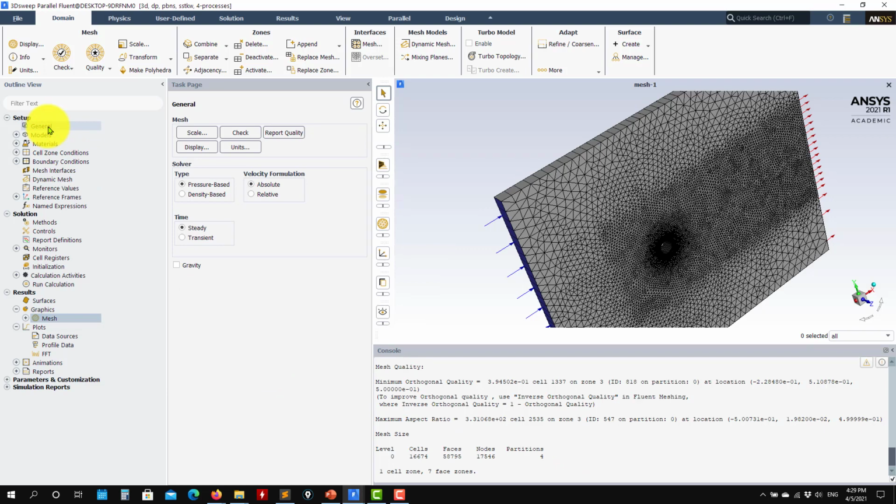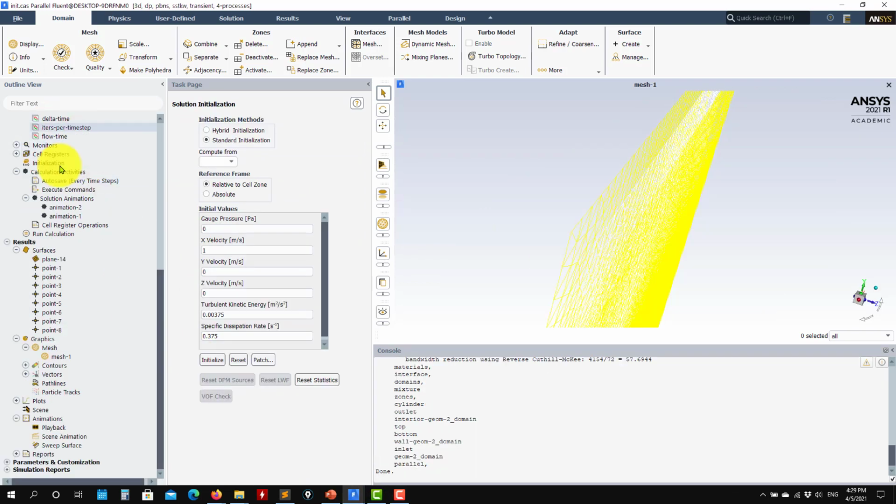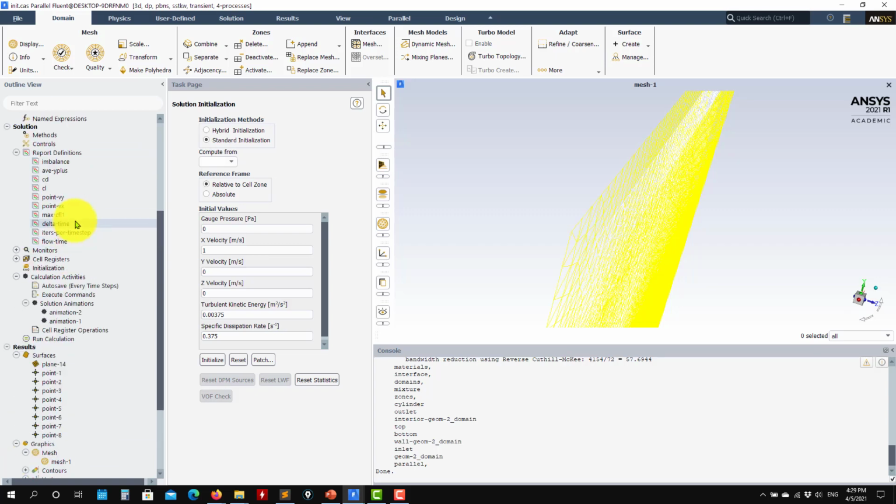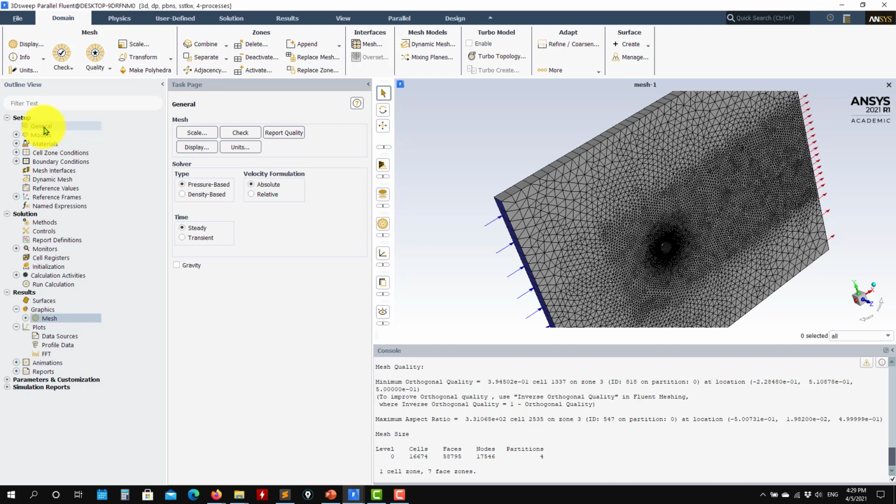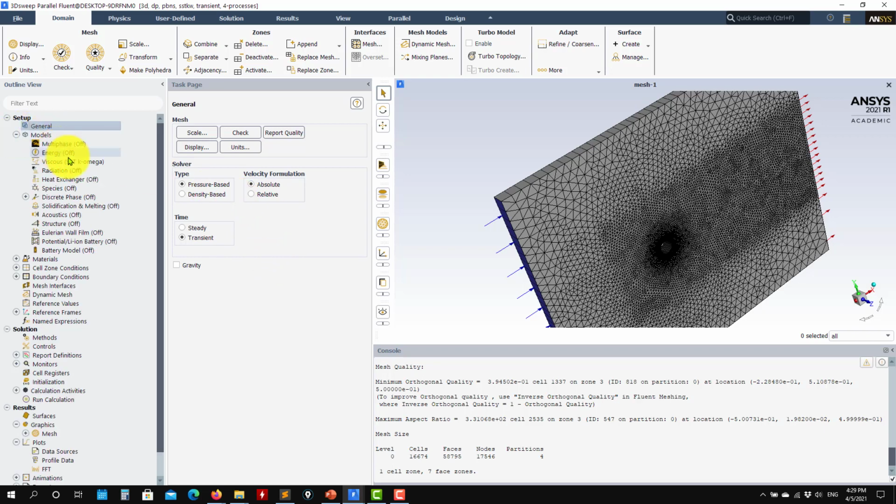So I'm going to show you a basic case setup now. I'm not going to show you all these options that you have here, just reopen this case or do the setting to see everything, but we have explored that. See that in general, the new modification that you need to do is here. Now this is a transient, so now you have the time derivative. The rest is exactly the same. You go to viscous models, you want to enable energy. It's exactly the same as we have done previously.